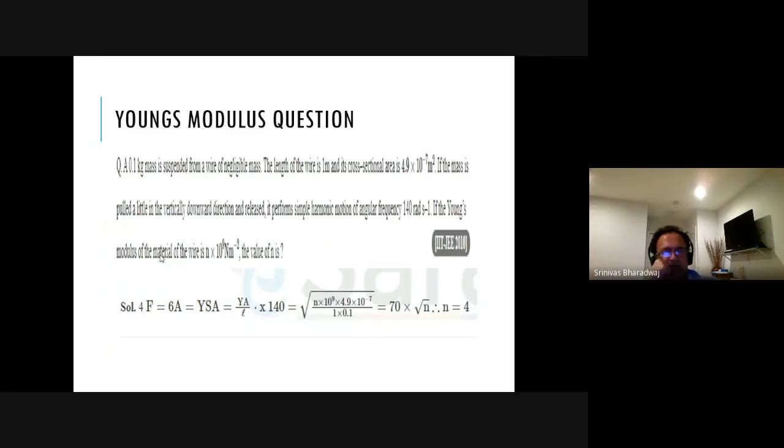What does that give you? Omega square equals K over m. That is used to calculate the K, because you know omega is 140, you know m is 1 kg. Okay. So now you know F equals Kx. Now what is F? 1 times 9.8. And so 1 times 9.8 equals K times X, right? But then